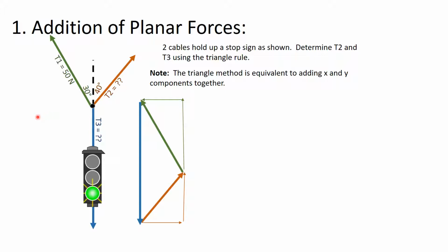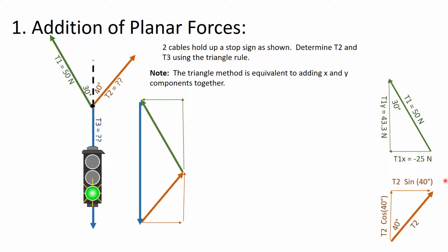Okay, so if you've taken physics, you have probably learned splitting everything into components. So you have your force, which is a tension or compressive force, and you take that force and you split it into the X component and the Y component, and you're going to do this for each piece of it.